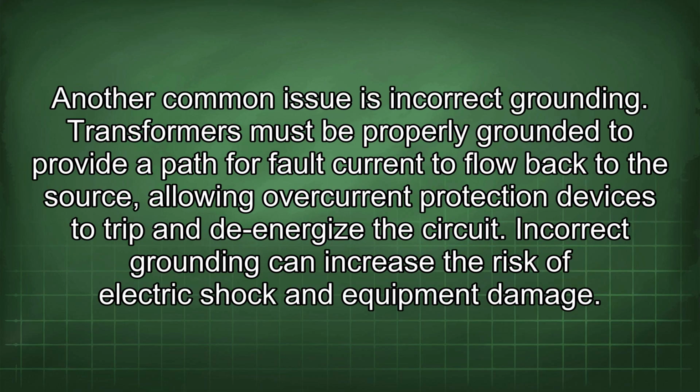Another common issue is incorrect grounding. Transformers must be properly grounded to provide a path for fault current to flow back to the source, allowing overcurrent protection devices to trip and de-energize the circuit. Incorrect grounding can increase the risk of electric shock and equipment damage.